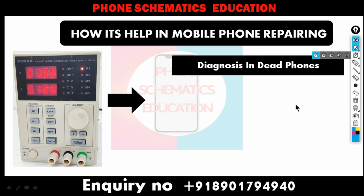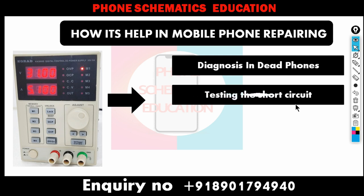Now after this, our next point, testing the short circuit. A DC power supply can identify a short circuit in a mobile phone, I mean the motherboard, by observing the current consumption.